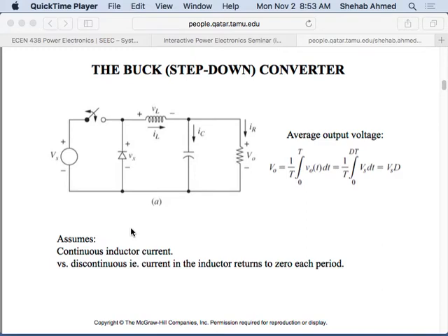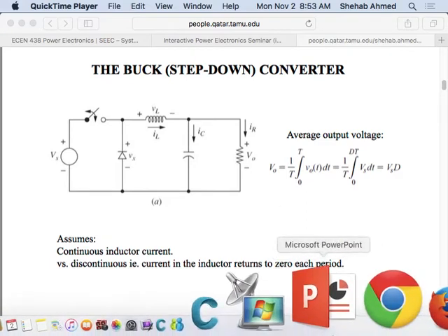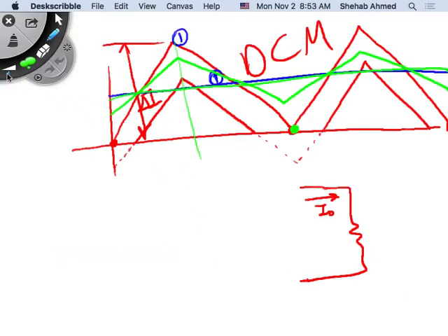And we will discuss discontinuous mode as well. There's nothing wrong with operating in discontinuous mode, right? So what's the difference between continuous mode and discontinuous mode from an inductor size perspective? Exactly. Discontinuous mode has a smaller size inductor, so L is small. If, for some reason, from a design consideration, you need a small inductance because of space, or because you cannot find the proper value of inductance, then that's a good way to go. There's nothing wrong with that, right?